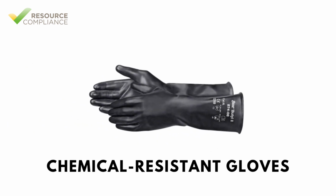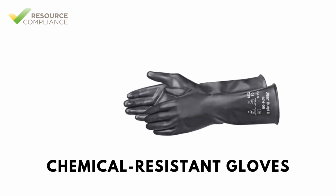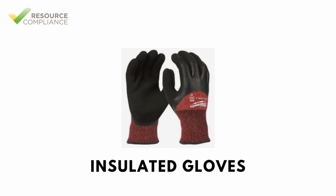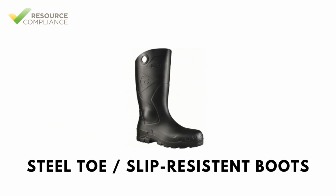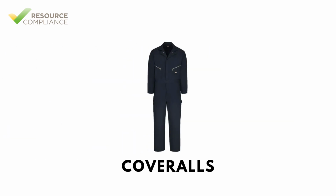Chemical-resistant gloves must be worn for handling refrigerants, condenser treatment chemicals, and battery acid. Insulated gloves are needed for protection from extreme cold. Electrical-rated gloves are required when performing energized electrical work. Steel toe or slip-resistant boots may be required to protect against dropped tools, heavy equipment, and slips on icy or wet surfaces. Coveralls made from durable, flame-resistant fabrics are recommended in areas with welding, cutting, or arc flash risks.